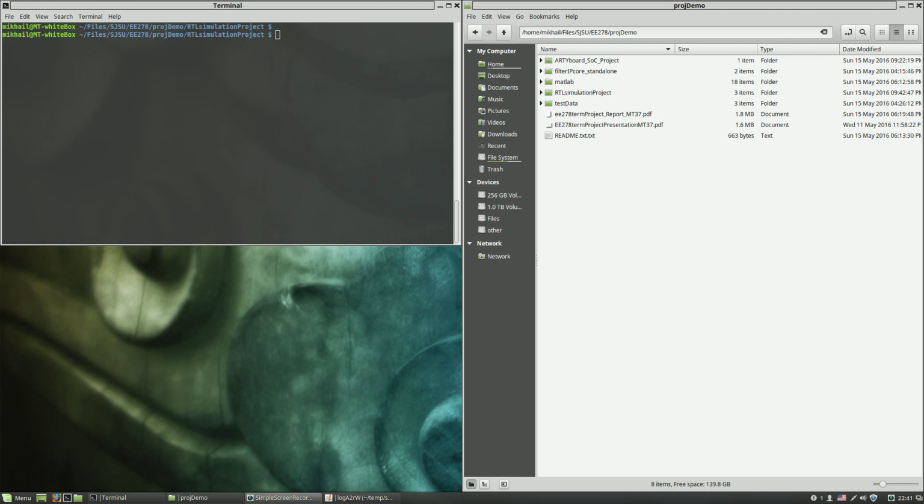This is a demonstration of results of EE278 term project taught by Professor Chang Choo in spring 2016, an adaptive FIR filter. In scope of this project, I have implemented an FIR filter with LMS algorithm as Verilog RTL code, performed behavioral simulation and packaged the code as Vivado IP core, and used it in a simple SoC design to demonstrate the result in hardware.